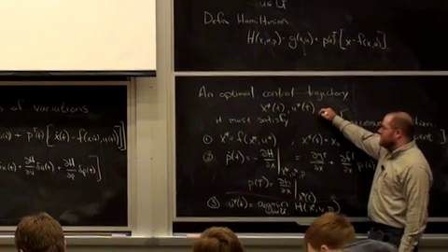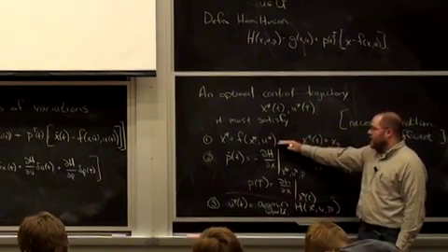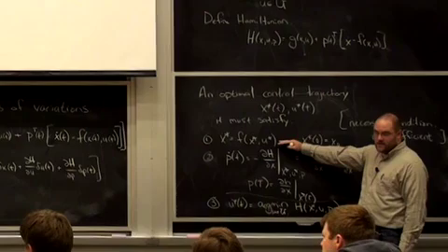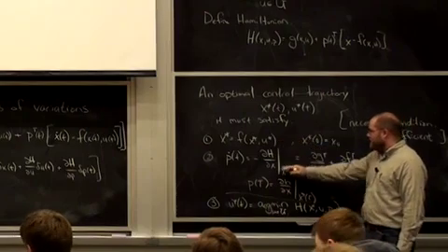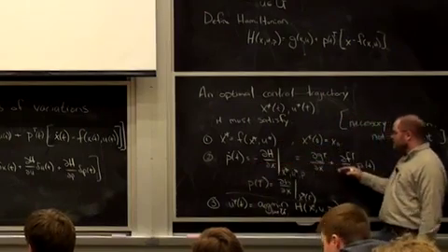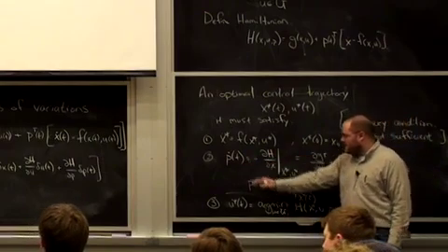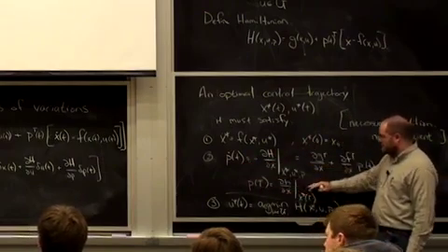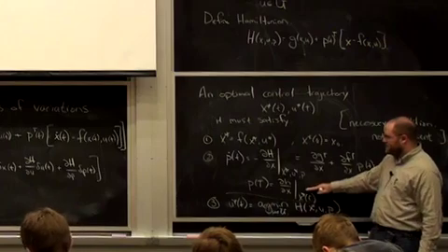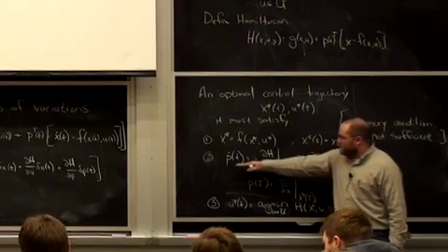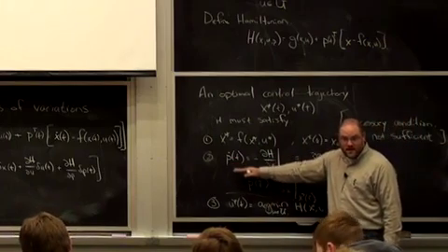Okay, so Pontryagin's minimum principle says that if my constraint x dot is satisfied, and if I can integrate this p dot backwards in time from some final conditions, which come from the same basic variation argument, then I've found Lagrange multipliers which satisfy that constraint.